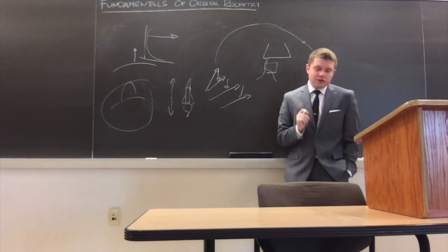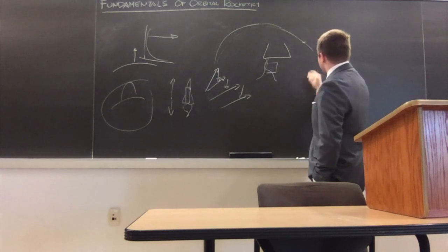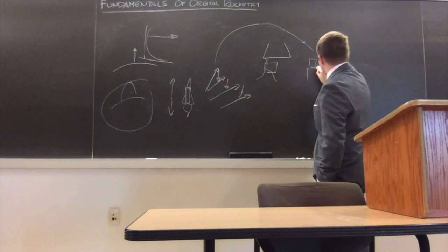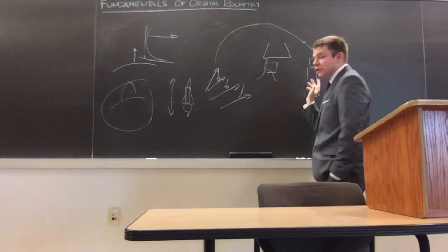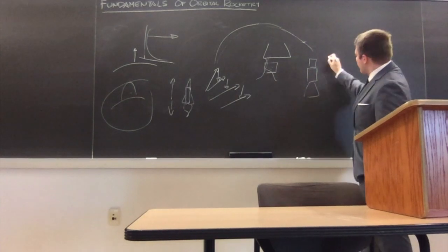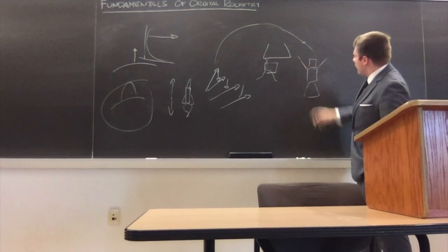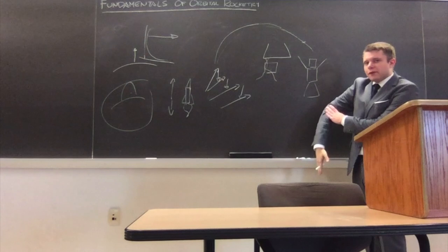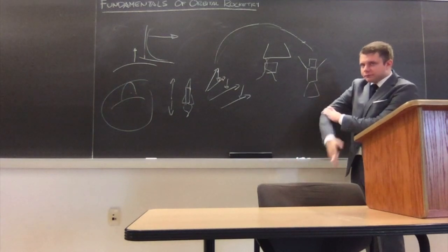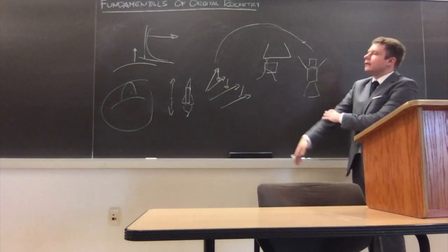So what most rockets generally do is they will actually physically take the entire motor, and this is especially true for liquid rockets, and they will have actuators built into it, and they will push and pull the rocket motor itself around. They will vector the thrust in order to steer it.